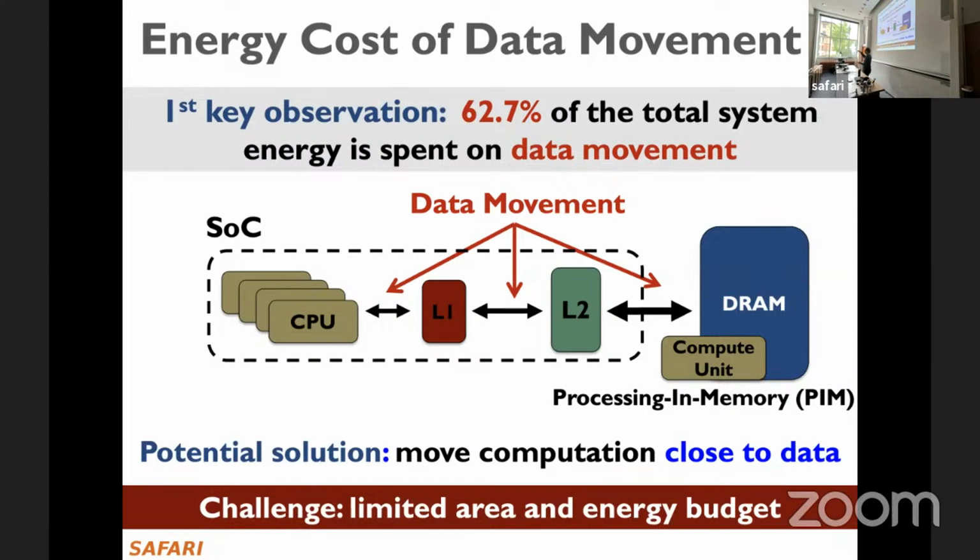But if you have multiple dies stacked together, then there's no place for the heat to escape unless you actually have a cooling solution between the dies, which tends to be expensive. So in general, not employed. So you have a thermal problem in these chips. So you cannot put any kind of computation unit in the logic layer, because if you put, let's say, a 4 gigahertz or 5 gigahertz computation unit that's consuming a lot of power, then you have a thermal breakdown in the entire stack. And that's not allowable.